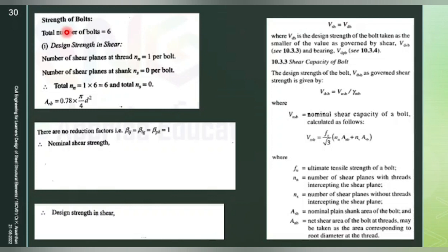The bolt. Then you should substitute the diameter of the bolt only. When dealing with the plates, the hole is drilled on the plate. When you are designing the bolt, you should apply only the diameter of the bolt.